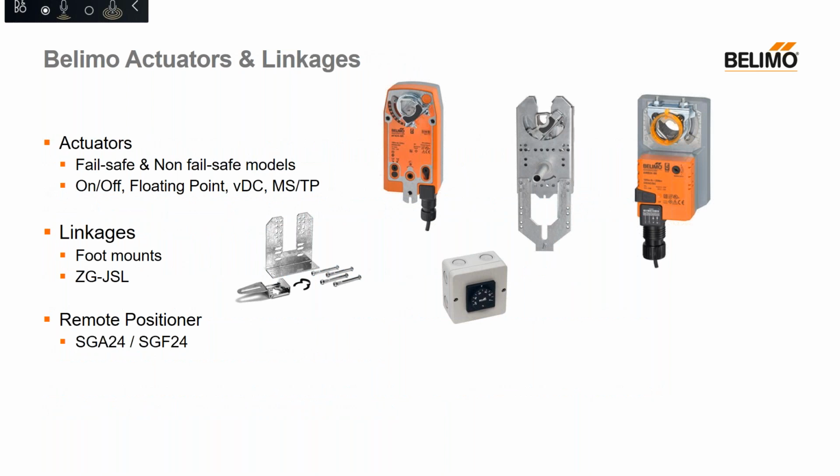Belimo also offers ways to improve your component devices with our actuator portfolio and accessories. For actuators, we have fail-safe and non-fail-safe models that range from 18 inch-pounds to 1400 inch-pounds, giving a very wide range of solutions for your control dampers. Some control signals we offer include, but are not limited to, on-off, floating point, VDC, and we have a range for BACnet applications. We have linkages that include foot mount solutions. Also, the ZG-JSL pictured between the two actuators is a great way to solve difficult mounting situations. It has a built-in shaft that allows for direct coupling.